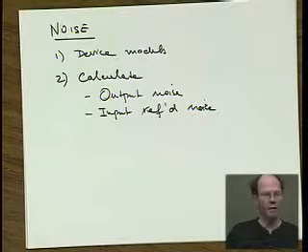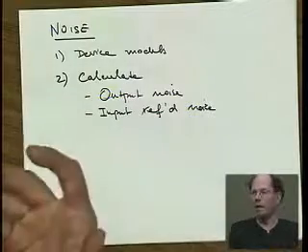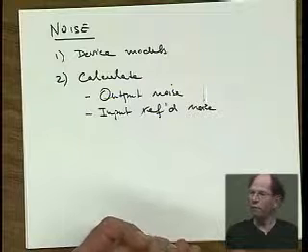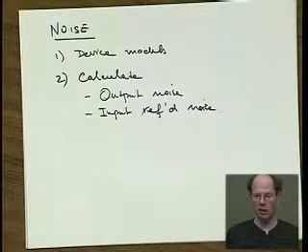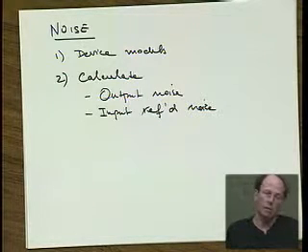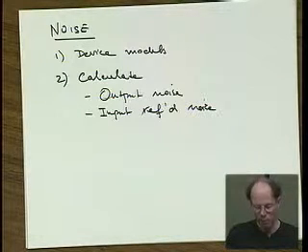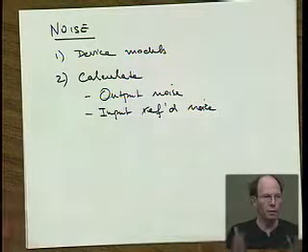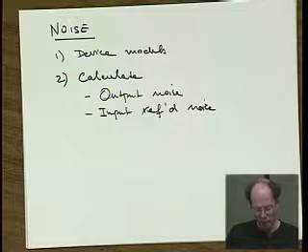And very often that's a very convenient metric, because if we have a sensor or a radio or whatnot that produces a small signal, we can compare that to the input referred noise of the amplifier we're going to use, and we can tell right away whether that noise is going to be a big problem, destroying our signal, or maybe not, right? Maybe it's okay, right? So it's a very convenient model. It's used consistently for all operational amplifiers. If you buy one, look up the data sheet, you'll find these numbers in there.